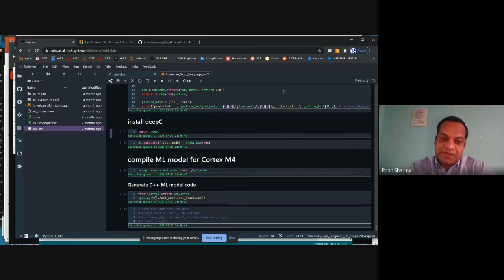It requires an OS to be installed, and on top of that you install Python and some of the higher level interpreters. With the lower, embedded devices like BLE Sense, you don't have that luxury because the memory available is only 256 kilobytes, right? So what runs on this is machine code, that you can use C++ to compile to the machine code of this board. And that's what we are facilitating.